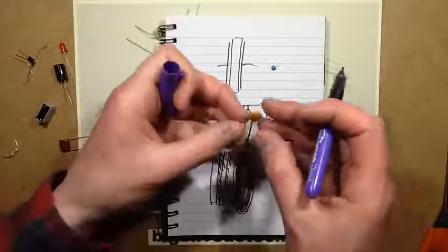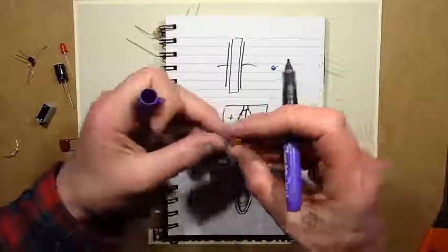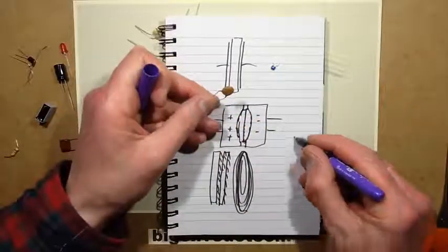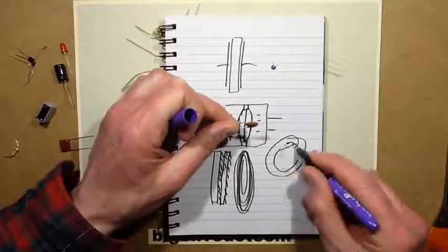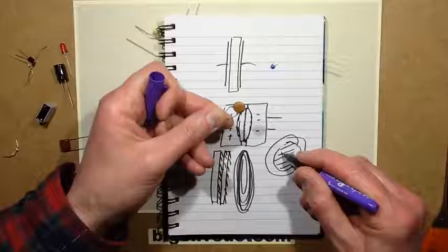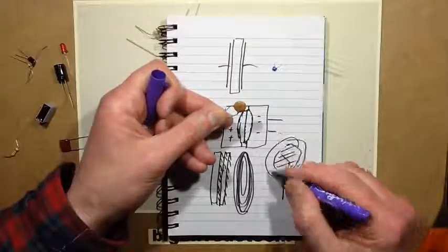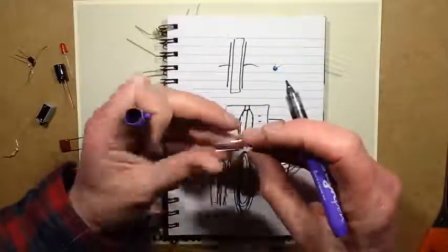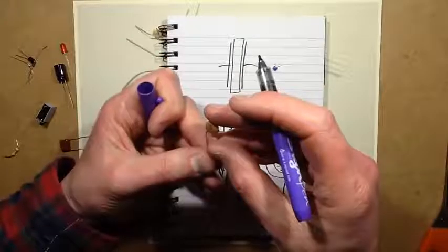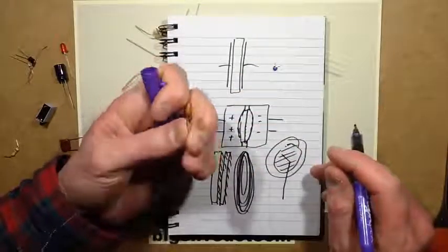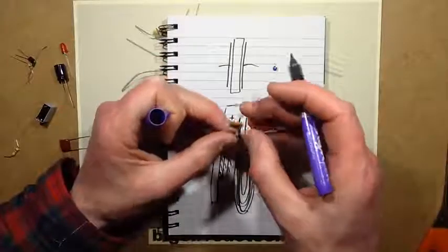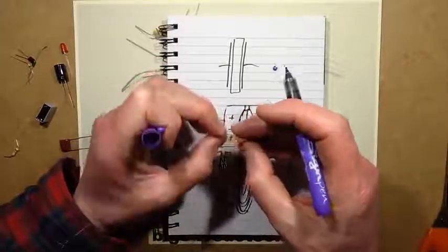This is a ceramic disc capacitor, usually quite low values. It's usually one of the simplest, and it usually is just a disc of ceramic with a conductive layer on both sides, and then an electrode that just comes across and comes off, and then it's dipped in insulation. But when you think that even this one is rated 10 nanofarad, and it's rated 1000 volts, but to get that 10 nanofarad, the insulation must be really, really thin inside that.